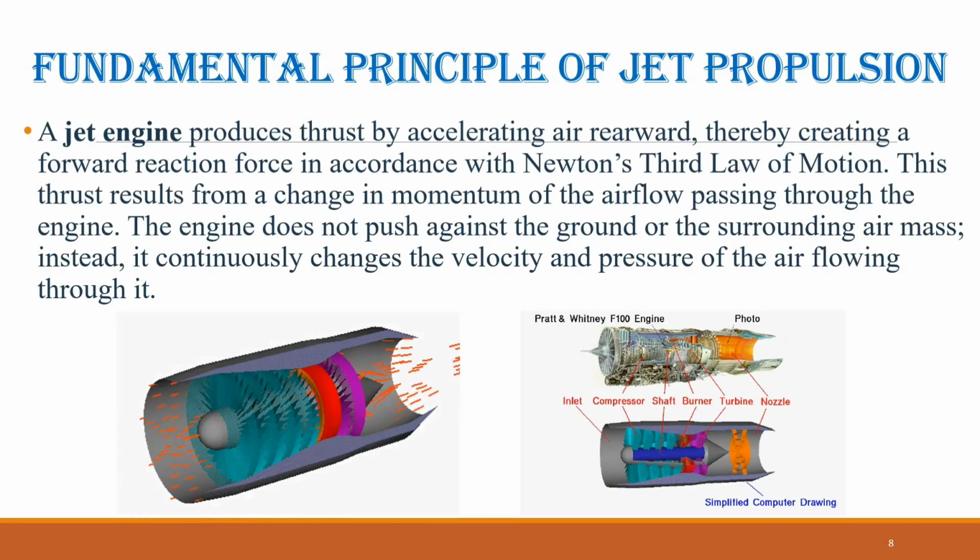In real engines such as the CFM56 used on the Boeing 737 or the LEAP engine on the Airbus A320neo, thrust is generated primarily by accelerating a very large mass of air through the fan at a relatively small increase in velocity. This design is chosen because accelerating a large mass of air slowly is more energy efficient and quieter.